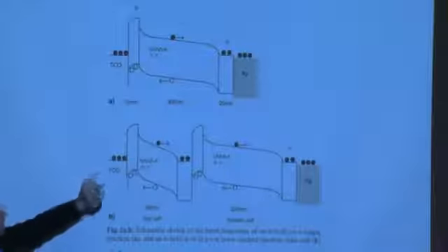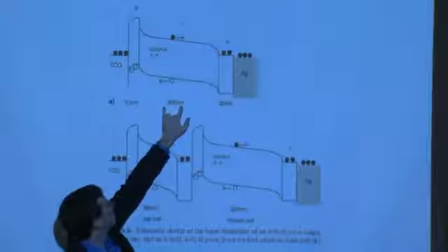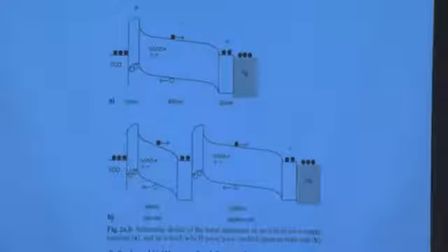Right here, we can see the P+ layer, or the P layer, the N layer, and then the I here in the middle, the lightly doped intrinsic layer. Note the band structure, or the band diagram, how it's arranged. And interestingly, the layer thicknesses here are on the order of 300 nanometers for the entire stack. It's rather thin, typically under a micron in thickness.